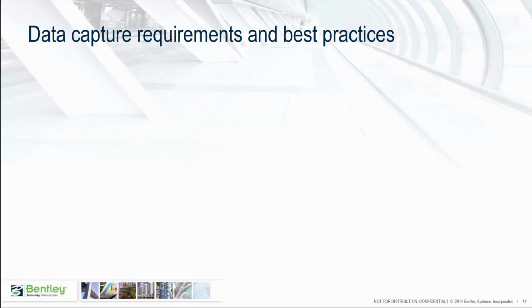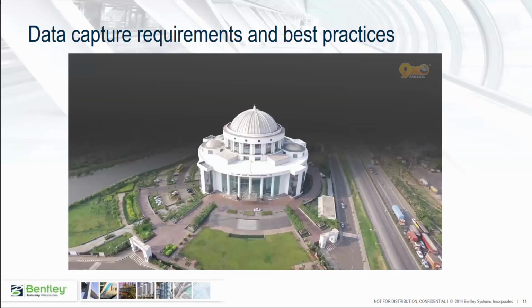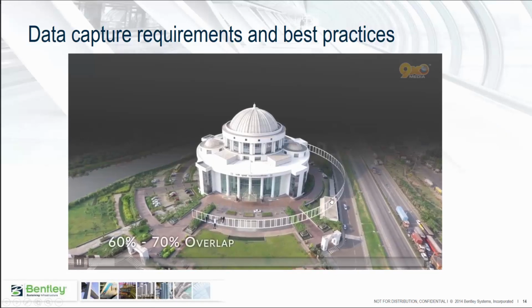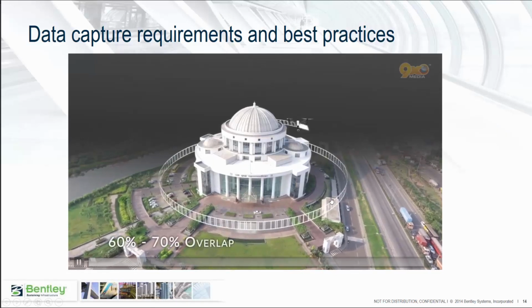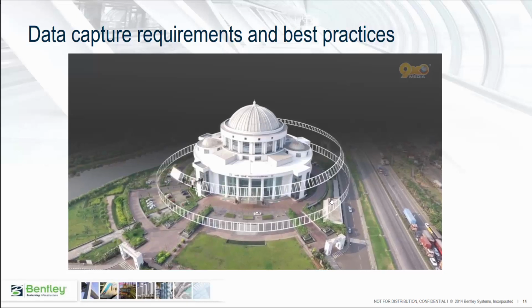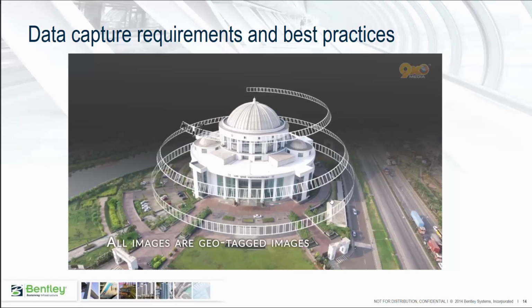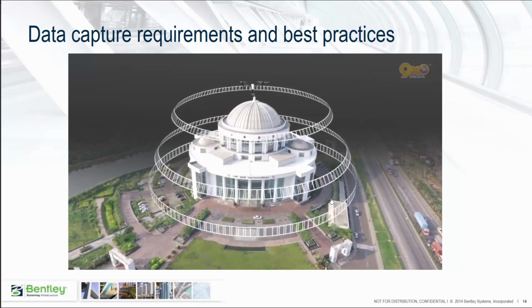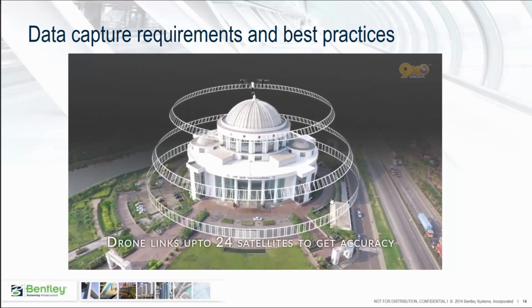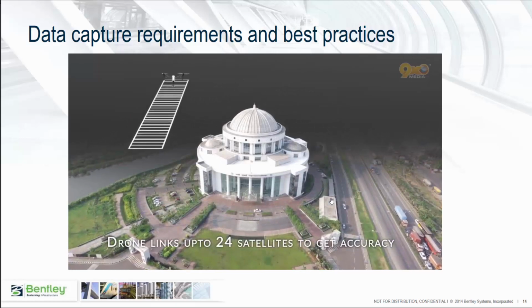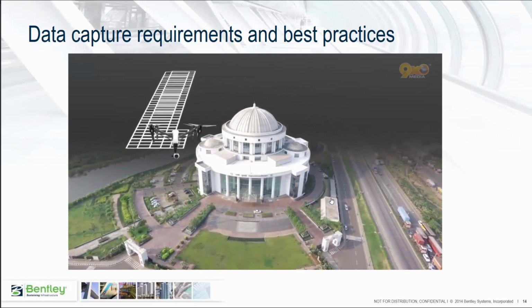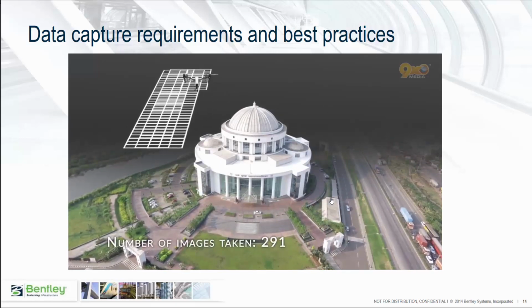This short video now shows you an exhaustive drone acquisition over a single building. Drone has been set to capture obliques at different angles, but also nadir imagery. Nadir imagery are important, especially if you plan on producing autophotos. So this is just a small example showing how capture of a single building can be done.